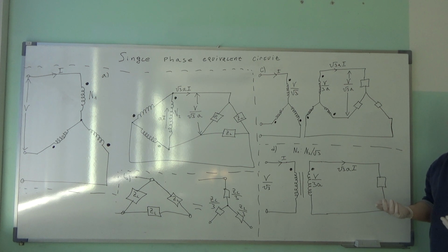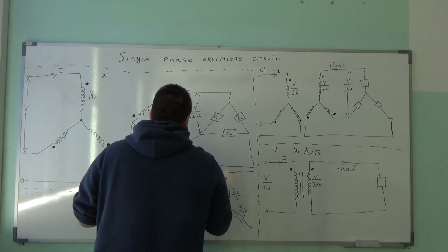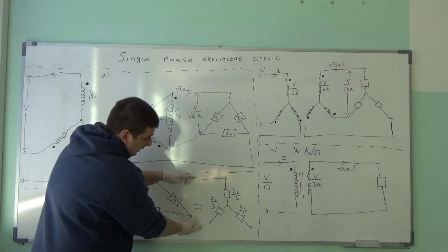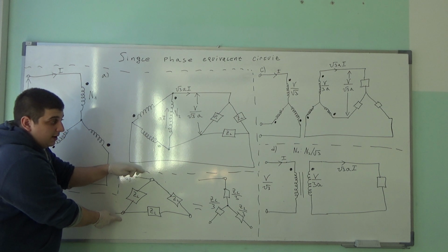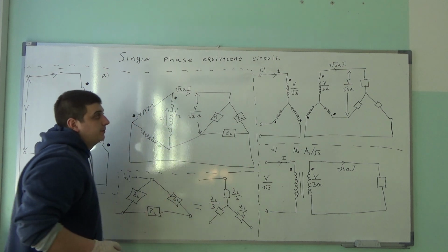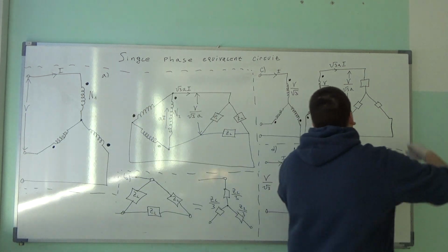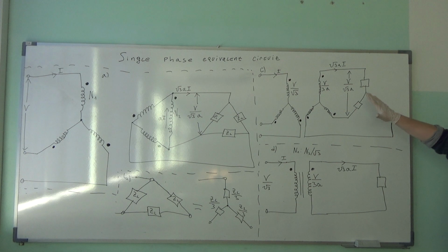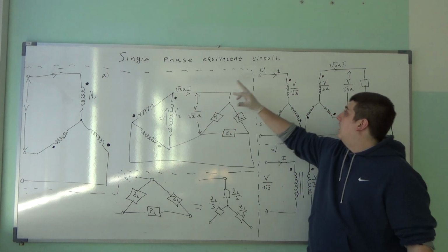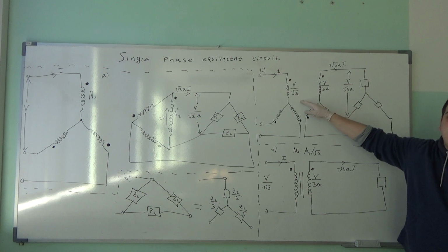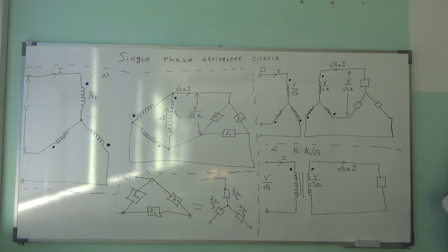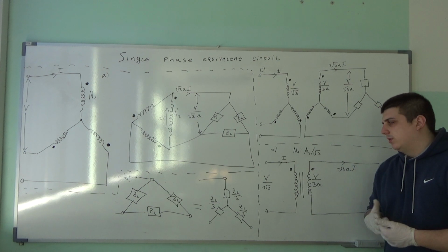And the line voltage from here is same as here. Because line voltage over here, from this, let's say this is phase A, this is phase B, is same as here. And that is over here. So now we transfer this to a Y configuration, delta to a Y. Now we have a Y and Y configuration, which is used in, for example, induction motors.